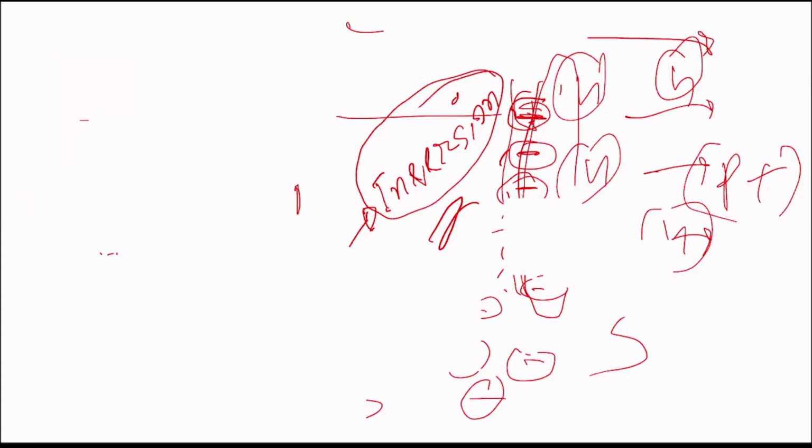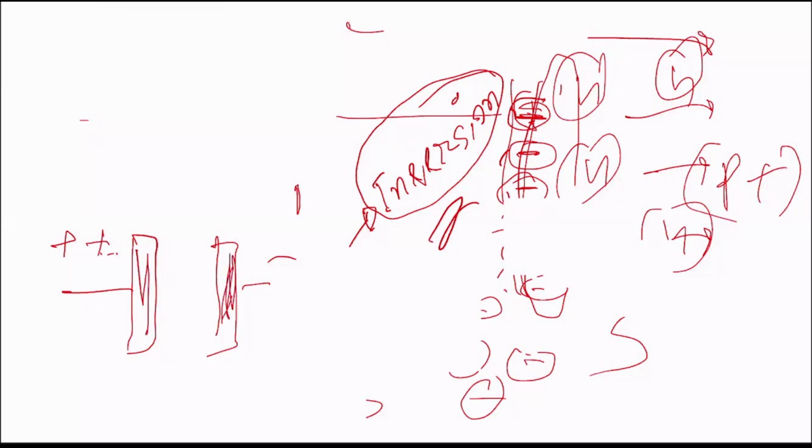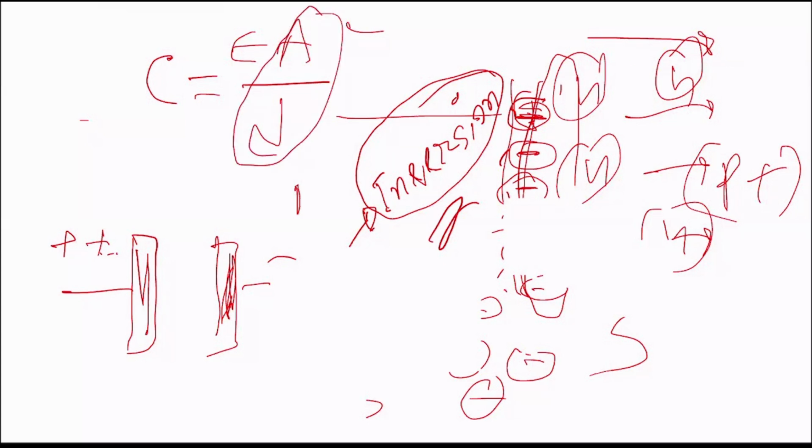Yeah, that's an excellent question, actually. So think about it. You can think of it as a parallel plate capacitor. You are just applying different voltage. As you increase more voltage, more charge is accumulated. If you look at the formula of a parallel plate capacitor, it depends on epsilon A by D: the dimension of the plates, their distance, and epsilon, which is basically the material parameter. So it doesn't depend on voltage. Even if you increase the voltage, a parallel plate capacitor's capacitance is fixed.